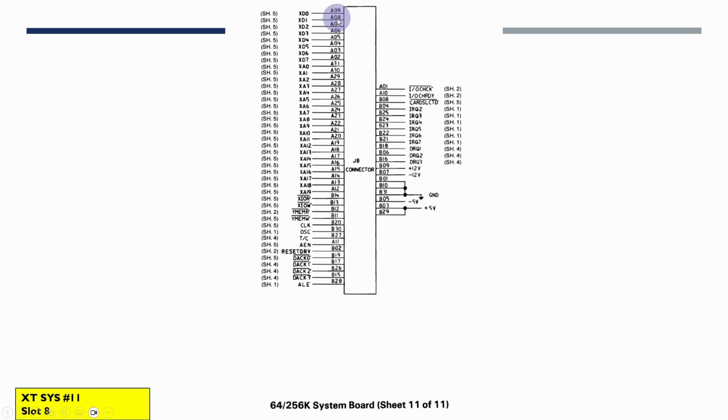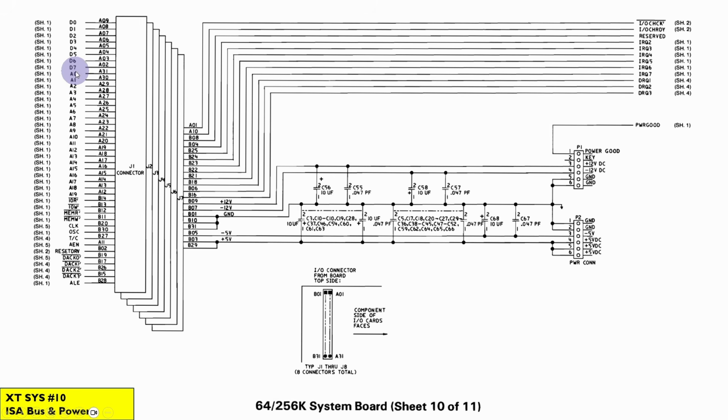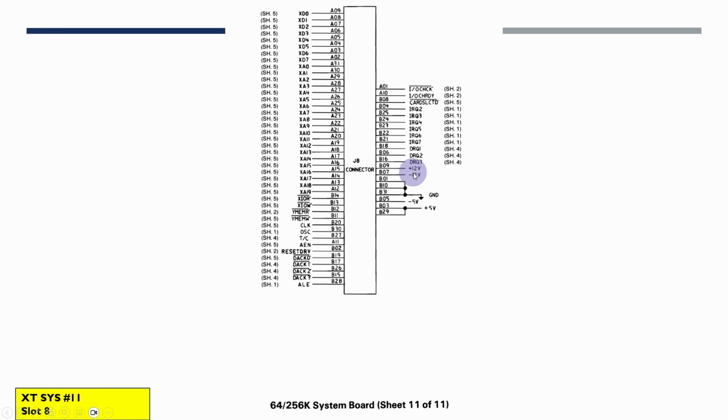But then on the slot 8, which was actually connected to the X bus, so you can see here this slot was actually on the X data and the X address bus, whereas the other ones are on the main data and the main address bus. So there was a bit of a difference in that, and cards that were going to be plugged into this particular connector had to enable this B08 card selected line, and this was used to configure some of the buffer directions that were needed for cards in this particular slot to work. Fortunately, this special slot 8 was dropped in later versions of PCs, so certainly PC-AT onwards we didn't have to worry about that.